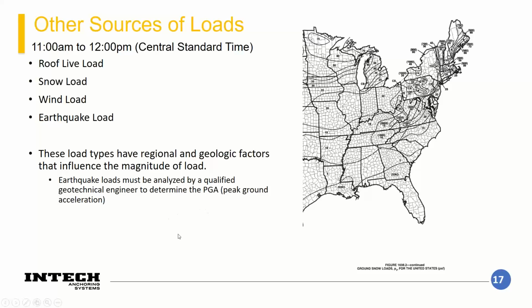This needs to be determined by a qualified geotechnical engineer, with the main important factor we're trying to uncover being the peak ground acceleration, because force is mass times acceleration. We need to understand what sort of acceleration these ground forces are exerting to be able to back-figure what that means for the load on my foundation.